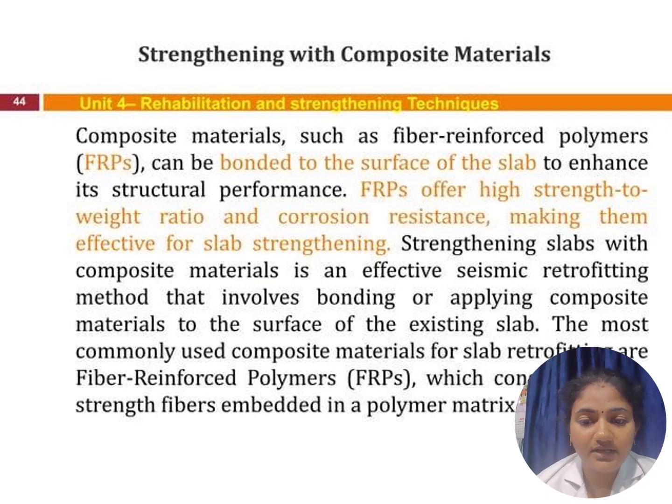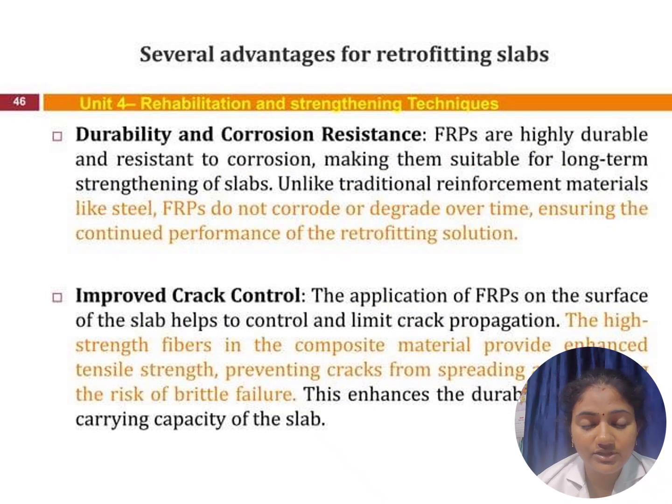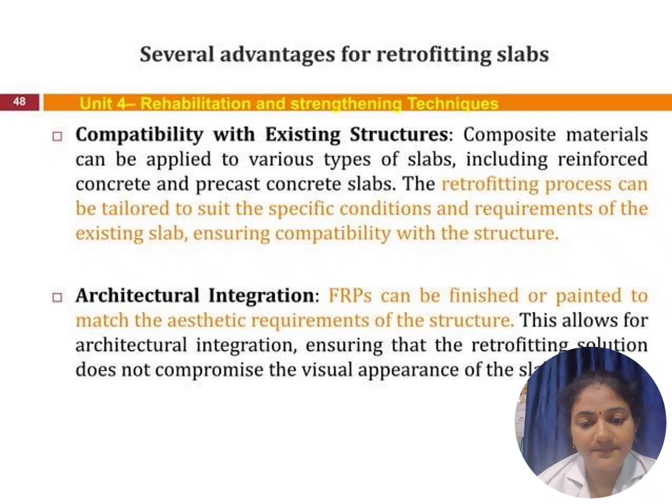And composite materials, that is fiber reinforced polymers, are applied to the surface of the slab to enhance the structural performance, making them effective for slab strengthening. And by using this, we can attain flexibility in design, durability, improved crack control, and increased stiffness, and quick and non-disruptive installation is done.